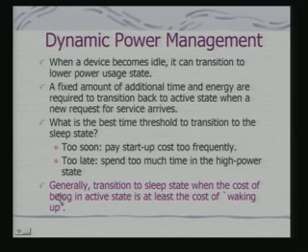So, what we say, it is a kind of a thumb rule: generally transition to sleep state when the cost of being in active state is at least the cost of waking up. So, that balances out the two things. If it is not so, then there is no justification for doing a mode switch. So, your controlling software has to make these estimates before taking these decisions.